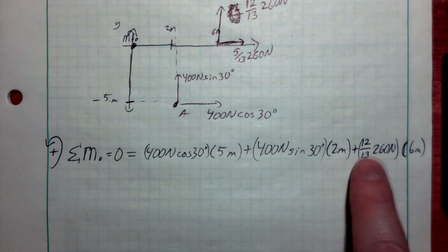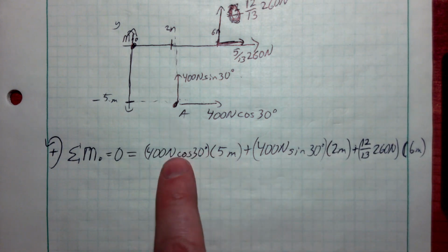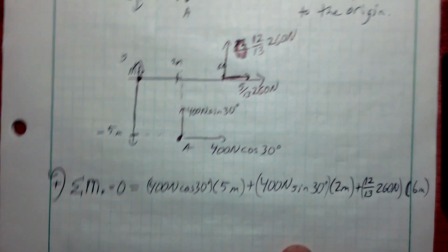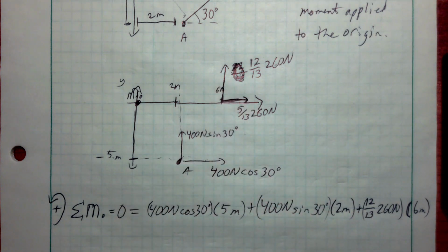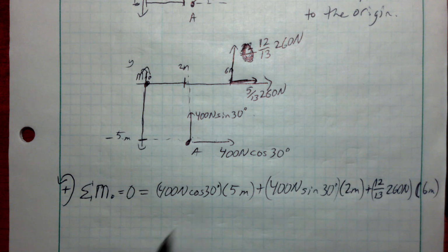That is 6 meters from the origin. Again, this is a y direction force, it's an x direction distance. Y force, x distance. X force, y distance. If you've resolved your forces into x and y components, then that rule will pretty well hold.